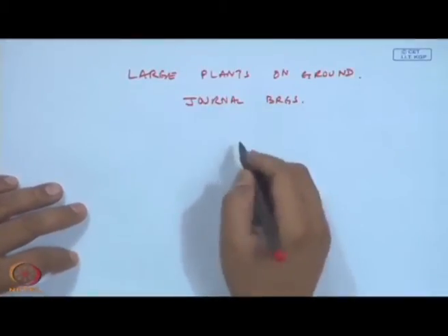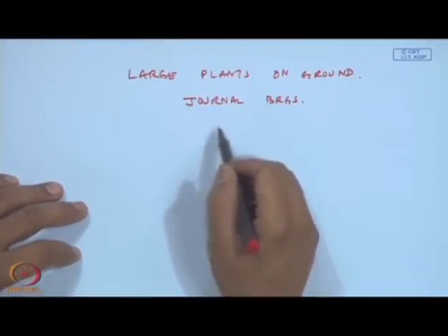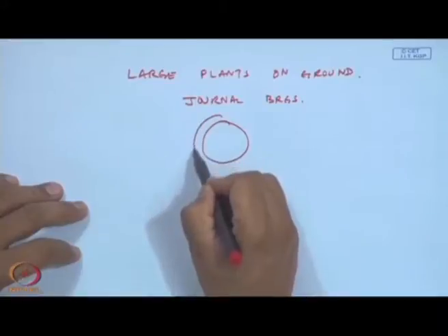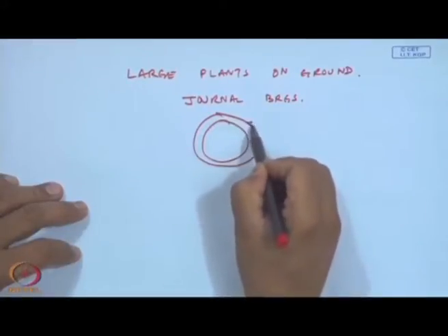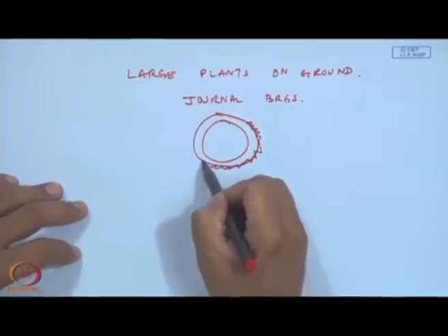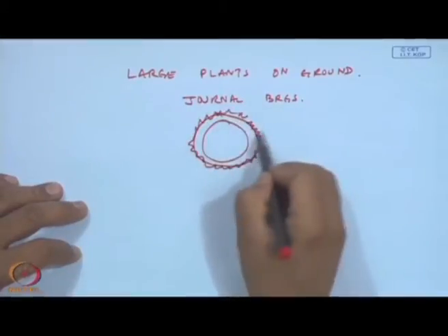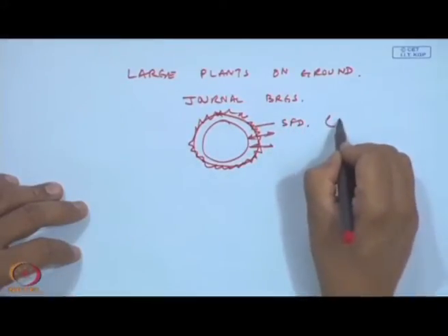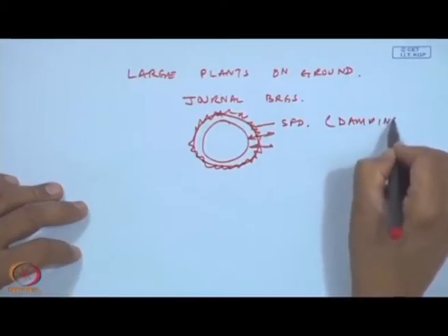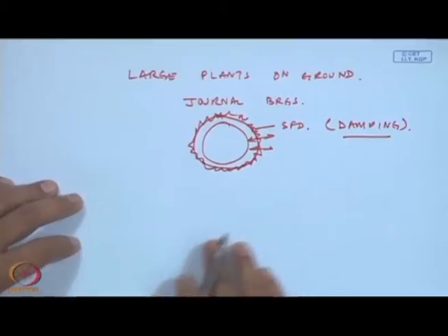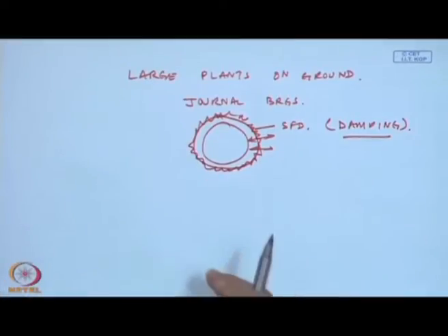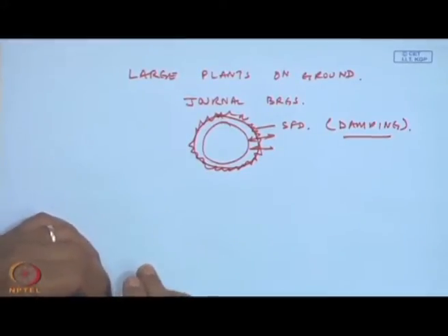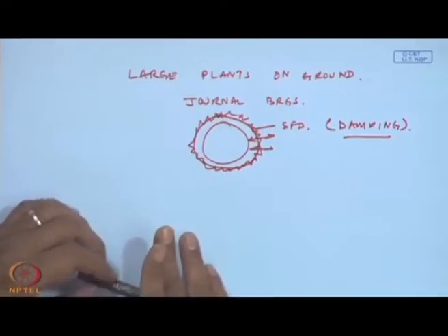And on these journal bearings, if I have squeeze film dampers, basically I have a system wherein I am squeezing and having a motion radially. I can put a squeeze film damper, and this is made to oscillate along the outer race, and basically I can introduce damping. And as you have seen, by introducing damping at the supports, the load which is carried at the supports does reduce, so damping has a very important role in rotordynamics, as it can reduce the support forces, and it can control instability.